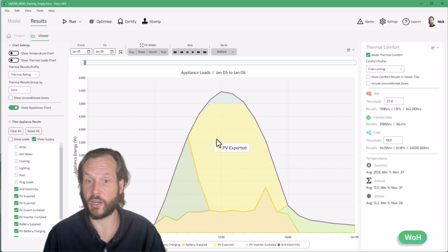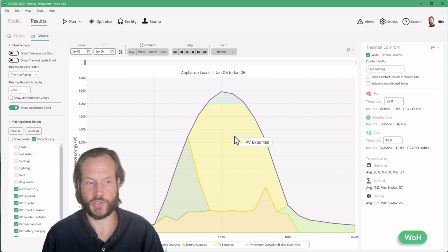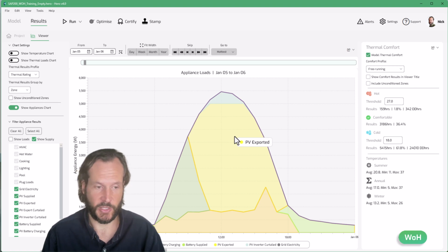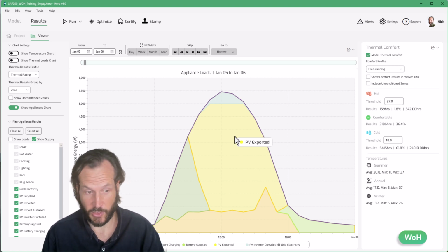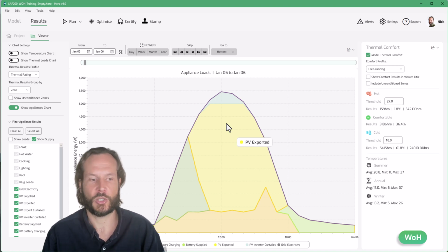There is a feed-in tariff that's given to you for exported solar PV. There is, however, a network export limit, which is defaulted to 5 kilowatts in Hero at the moment. Most electricity networks do limit the amount of solar exported to 5 kilowatts per phase, but on some networks I hear it's even none. And some homes you might have a 3-phase connection where perhaps you can exceed that 5 kilowatt capacity. So we'll add that in future, I expect. If the solar production exceeded that 5 kilowatt export capacity, again, that would be another curtailed energy.